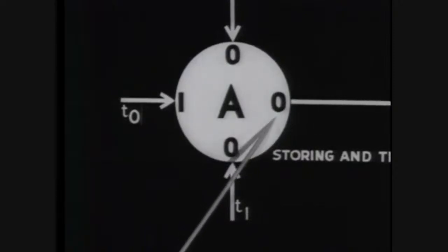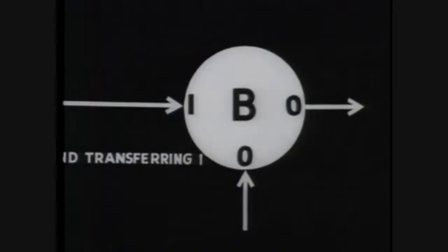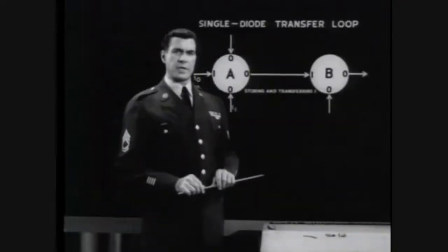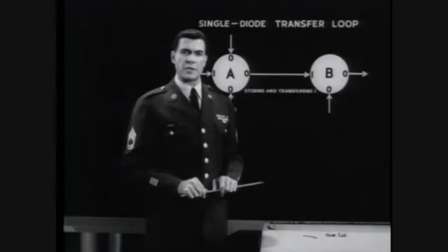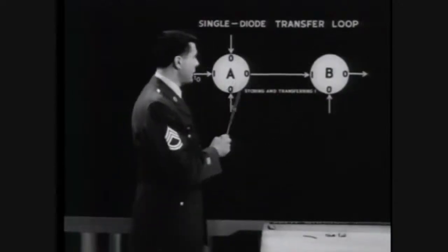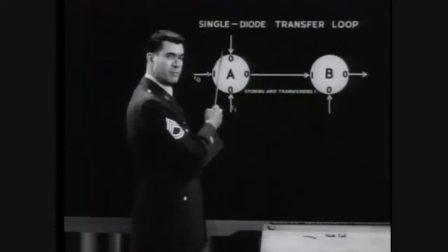And, as the diagram indicates, whenever the core is cleared to 0, an output occurs, switching core B to 1. But this means that either one of the dot inputs can bring about a transfer of the bit from A to B, the bottom one or the top.